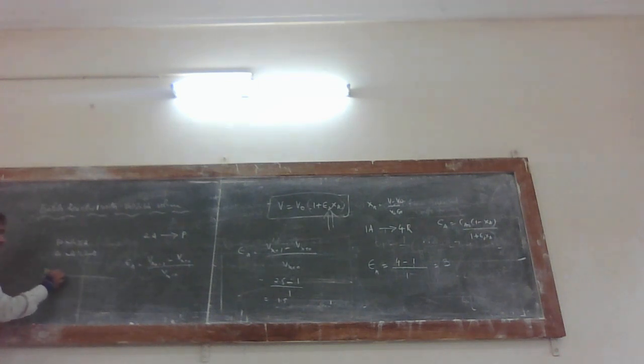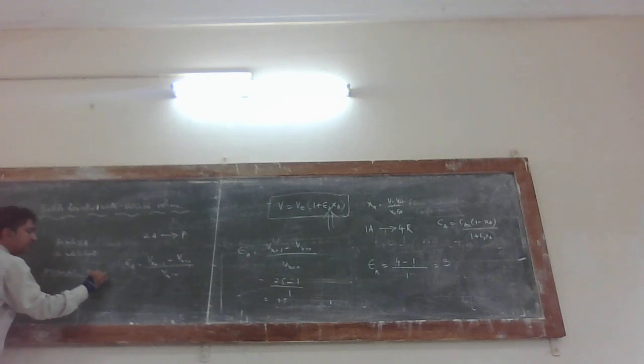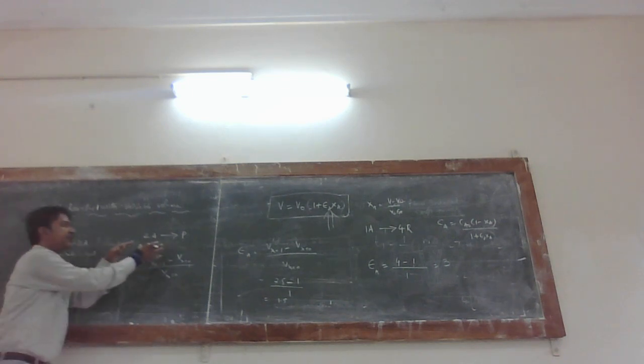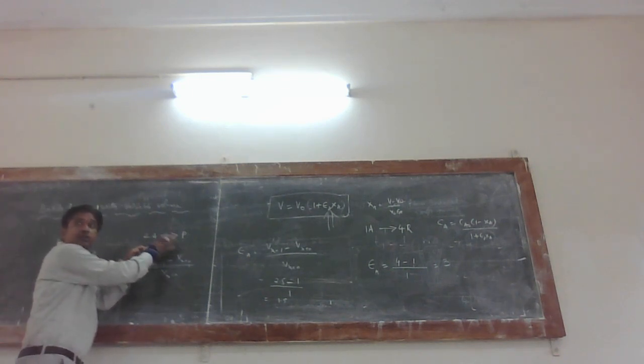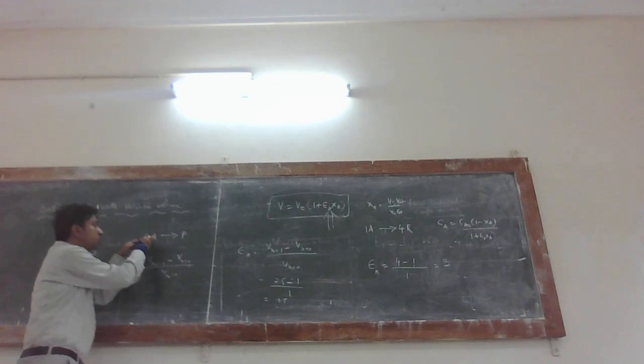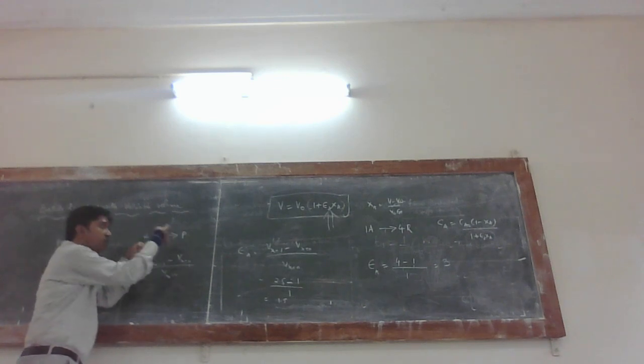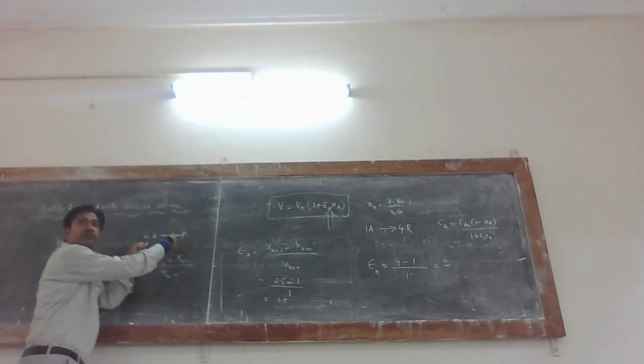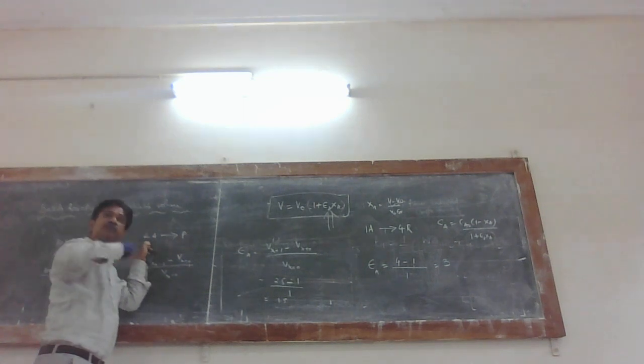At 100% completion, how many moles change? At 0% completion, how many moles change? Let us check with 100% conversion. Check out the reaction. Understand first: 2 moles of A becoming 1 mole. That means it is becoming half when I give 100% time for conversion.